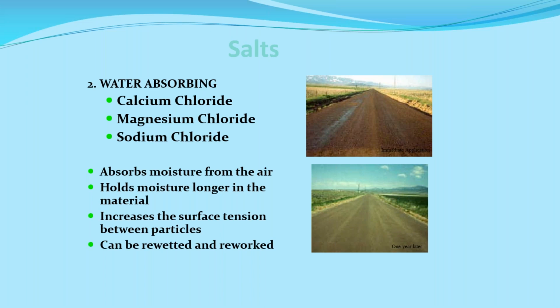So it might take 2 or 3 treatments on that roadway to get it up to where I'm at about 1/2 gallon or 3/4 of a gallon per square yard. The reason I do that is because I personally don't like running my equipment through the magnesium and the sodium when it's wet on the surface.